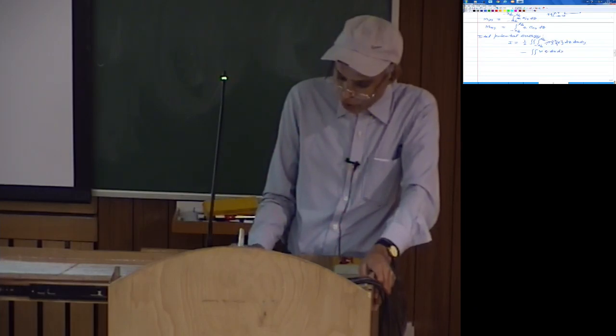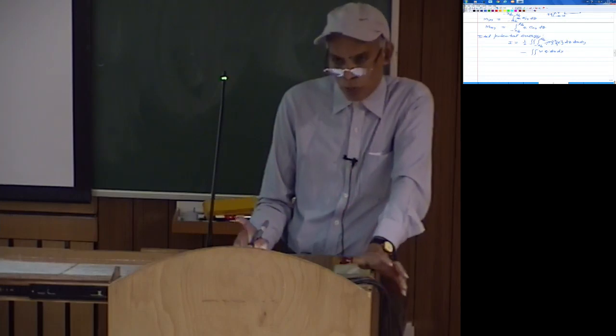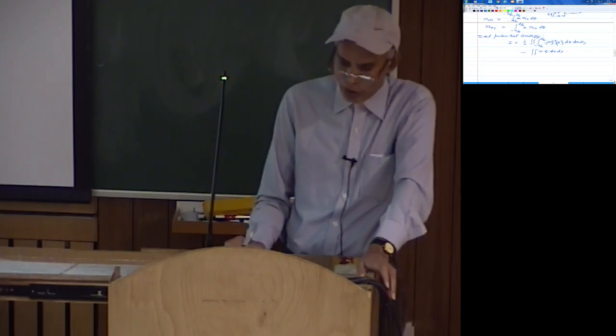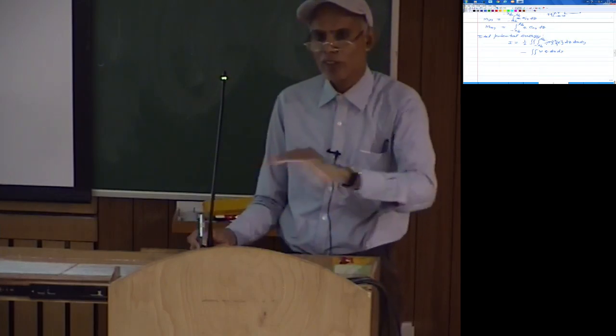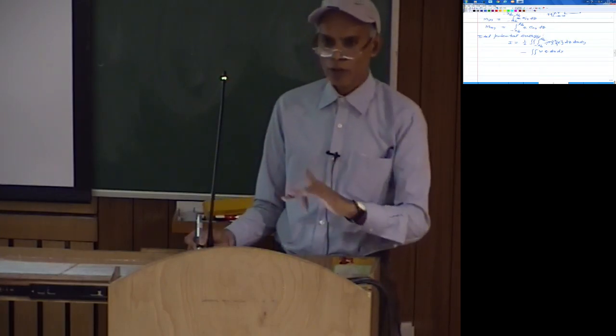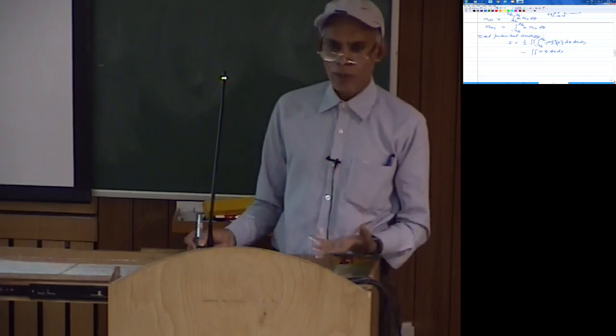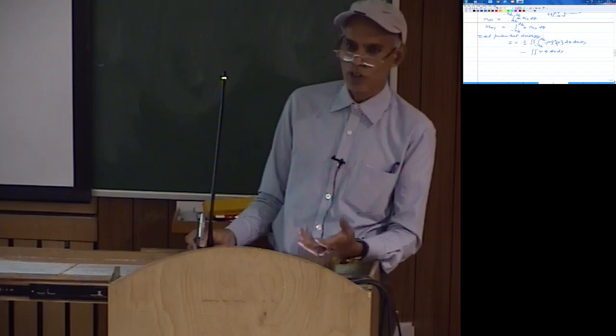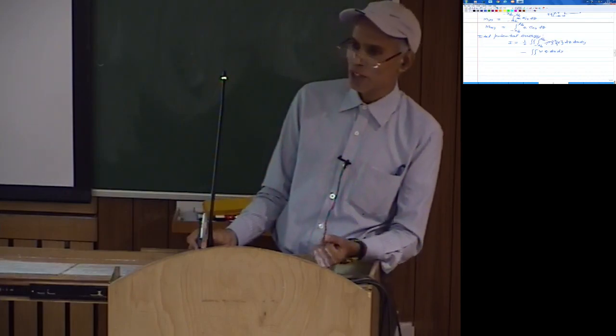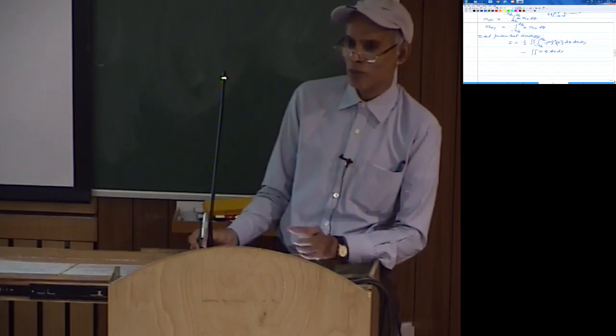So Q into dx into dy is the force, because Q is force per unit area, into W the work done, negative of that is the potential energy, and the integration is only over area, because this is acting only on the xy surface. Although it might be acting at the top or bottom, W is the same, we are assuming that W is constant through the thickness, so it really doesn't matter whether the load is at the top or at the bottom.